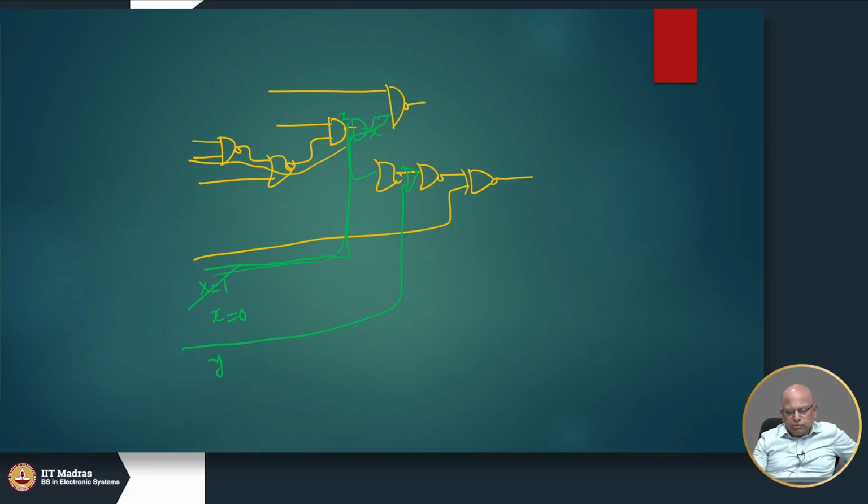It is not coming free of cost. See, the 2 gates or a few gates that I introduce may not take much area. Today we are not worried about the gates per se, but they are going to introduce some delay, and that may be something undesirable. And they may take a little bit of power, again that may not be such a big deal.